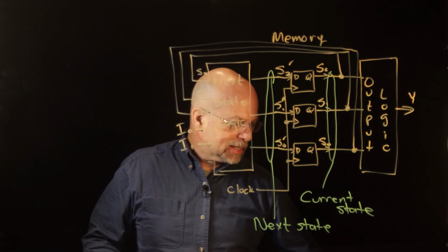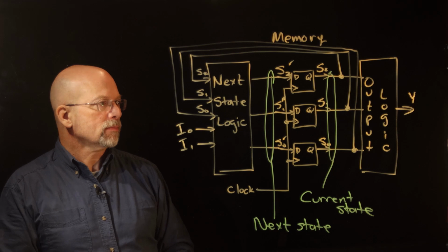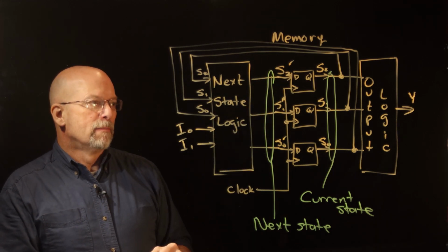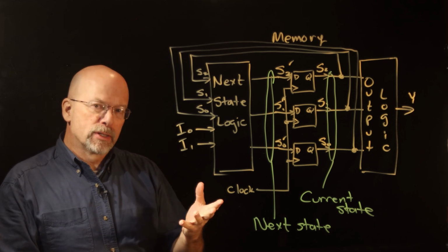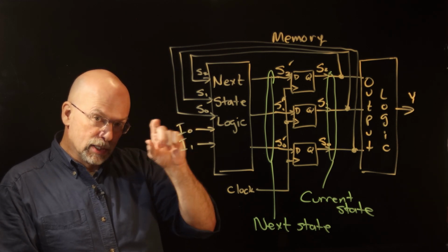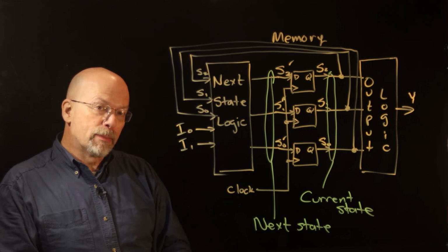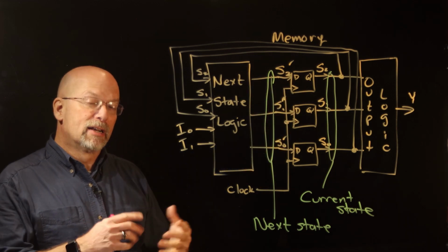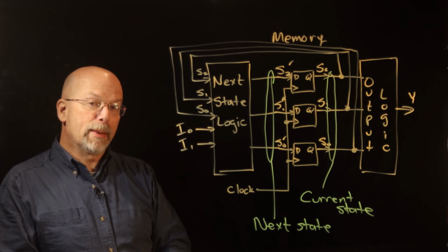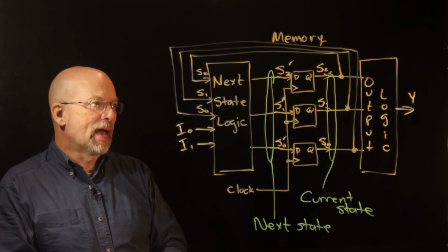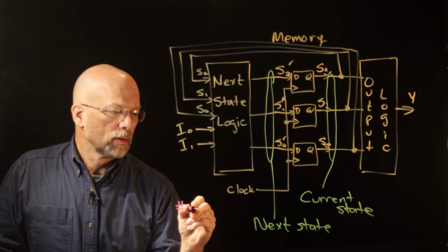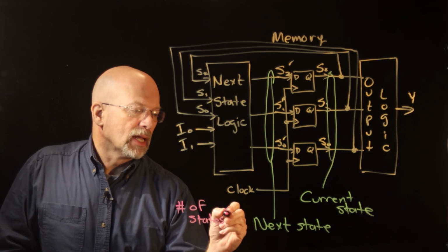All right. So let's take a look. Let's examine this architecture for just a moment. First of all, this system, and as I said before, we could have any number of flip-flops in the middle there. This system, we know, has at most how many states? Well, remember that each state, and those are represented in our state diagram with those vertices, the circles, right? Each state has to have a unique number that identifies it. That unique number that is being stored in memory identifies what our current state is, which one of those vertices we're in. I have 3 D flip-flops there. That's 2 to the 3 possible patterns of 1s and 0s that I can have inside of that memory, which means I can have at most 8 states. All right. So the number of states is less than or equal to 8.